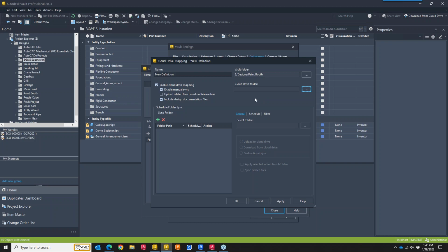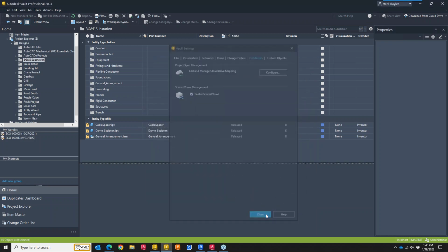Some things don't belong in the Construction Cloud, and that's fabrication quality models. If I have 2,000 components in an assembly, that does not belong in the Construction Cloud. PDFs of that belong in the Construction Cloud. Navisworks files of that belong in the Construction Cloud. Simplified factory assets from our factory design utilities could go into the Construction Cloud, but full fabrication detail models should not. Okay. But I wanted to show that there's quite a few tendrils inside of the Autodesk manufacturing products that enable a lot of these workflows and processes.